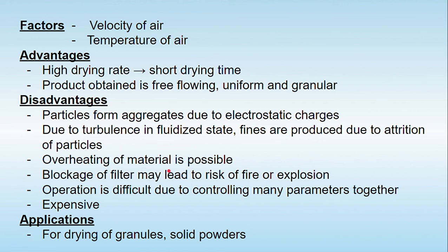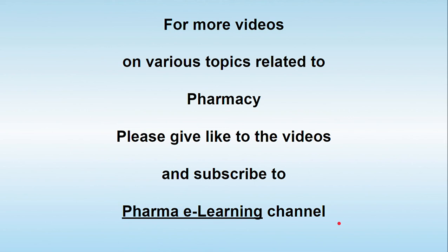Yes, sometimes overheating of the material is also possible. Yes, blockage of the filter bag may lead to accumulation of air inside, and because of that there's a risk of fire or explosion. Yes, the operation is somewhat difficult because we have to control too many parameters, and yes, this equipment is going to be expensive, but still, from the years together, today and in the future too, it is going to be used for the drying of granules and solid powders in the pharmaceutical industry.